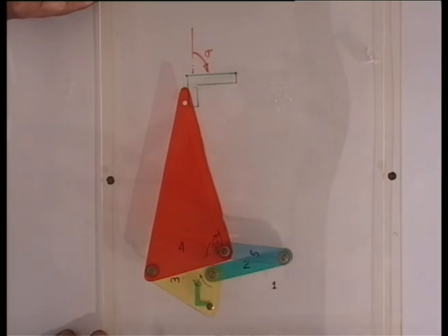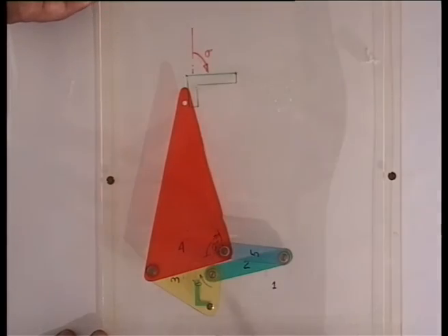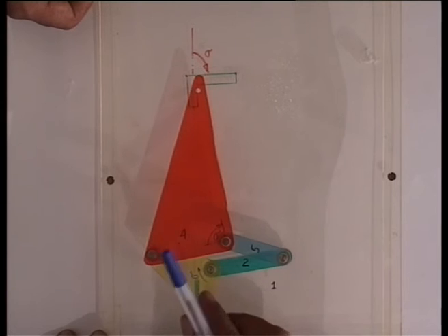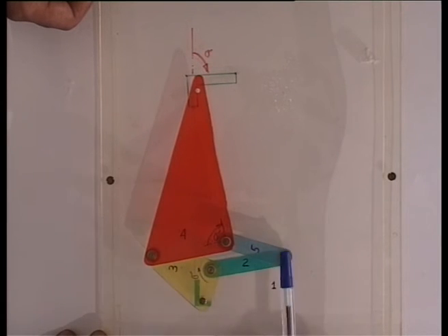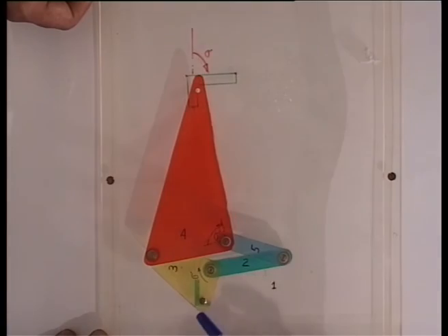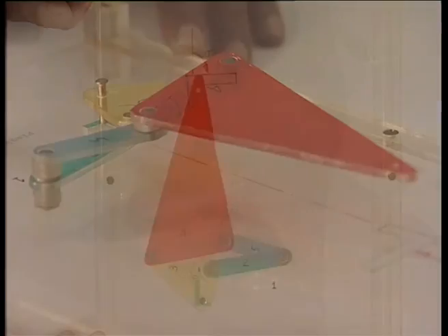As we see here, the L is okay, and here it has been rotated by 90° almost in the clockwise direction. The question is, for this given mechanism, that is, the link lengths are given and the angles are given, can we find out what is the ratio of these two figures and the orientation between these two figures? That will be our second example.